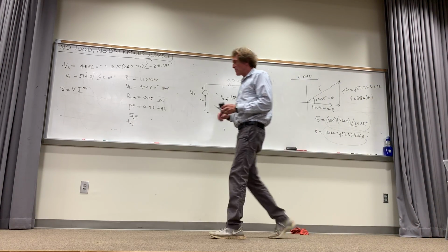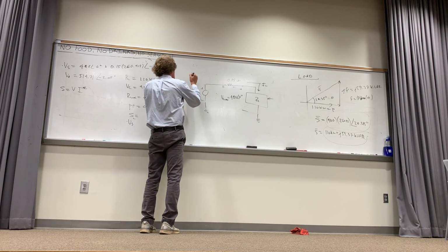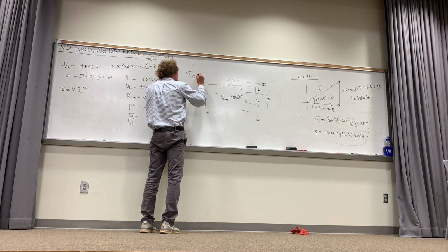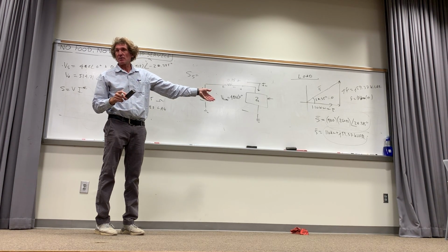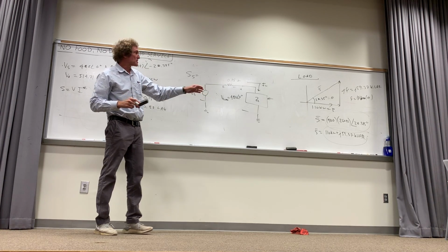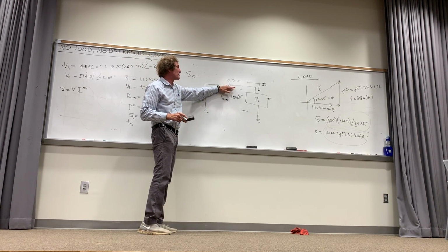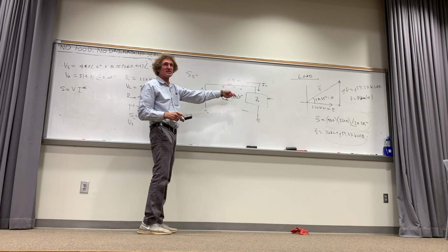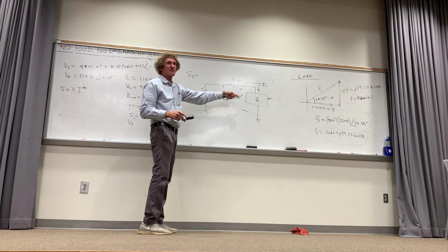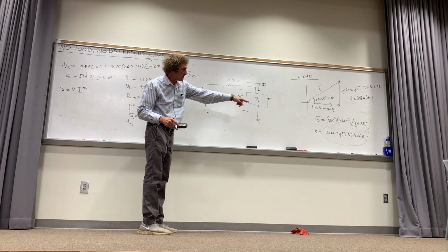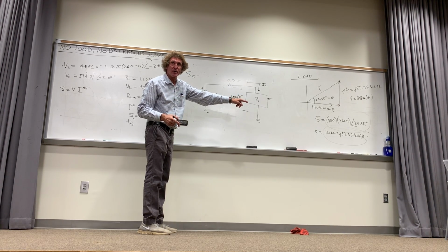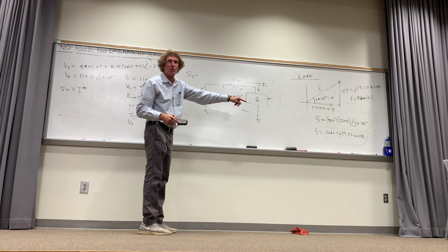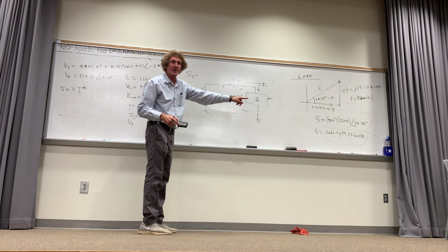But getting back to this problem, now if I want the total complex power supplied by the source, this is going to be supplied by the source. Well, you got the complex power dissipated at the load, correct, class? The complex power dissipated at the load is over there, right? It's 110 kW plus j59.37 kVAR, correct, class? If you just take that and do a conversion to polar coordinates, you're going to get the one above, right? Whatever that is, okay?